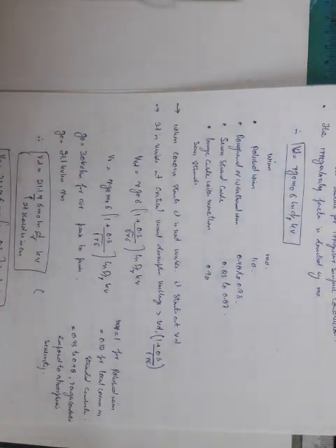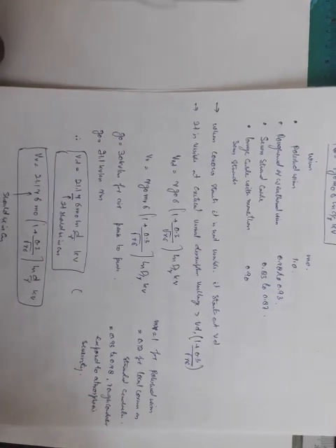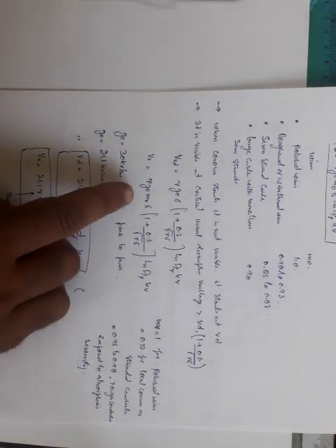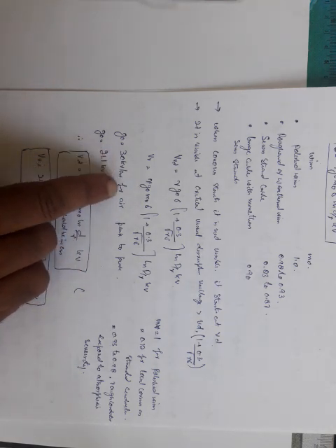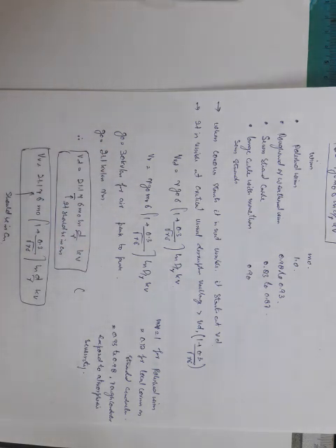and we will get the critical visual disruptive voltage. One more thing, in both the formulas you will see that this G0 is equal to 30 kilovolt per centimeter for air, and its value is peak. To get the RMS value, we have to divide it by root 2. So G0 will be equal to 21.1 kilovolt per centimeter, and its value is now the RMS value. So the disruptive voltage will be equal to 21.1 R delta M0 ln of D by R, and its value will now be in kilovolt, because G0 is in kilovolt per centimeter.